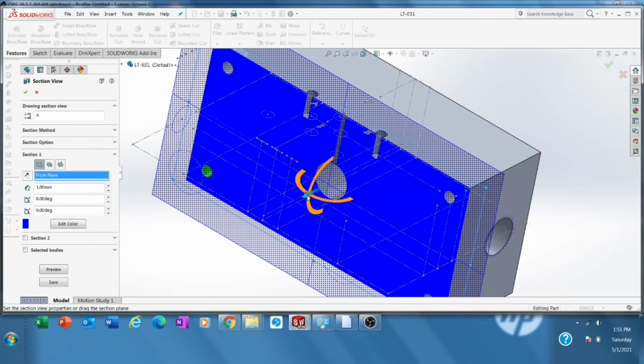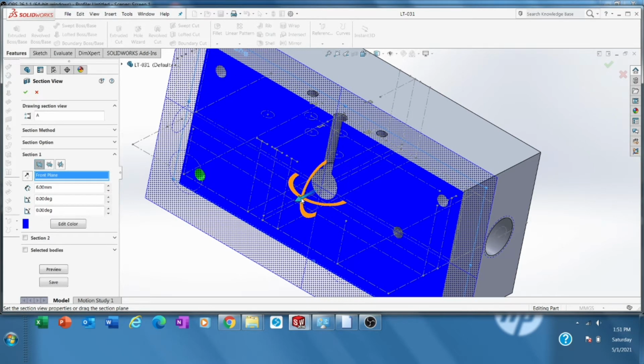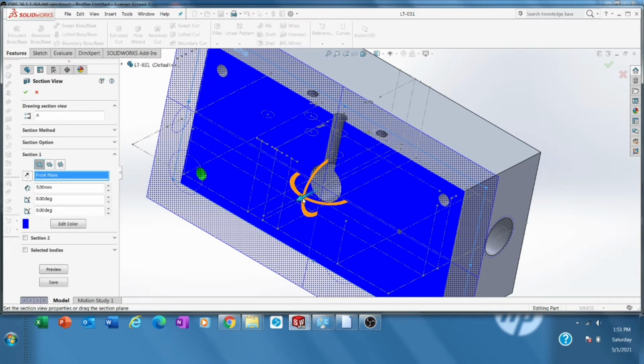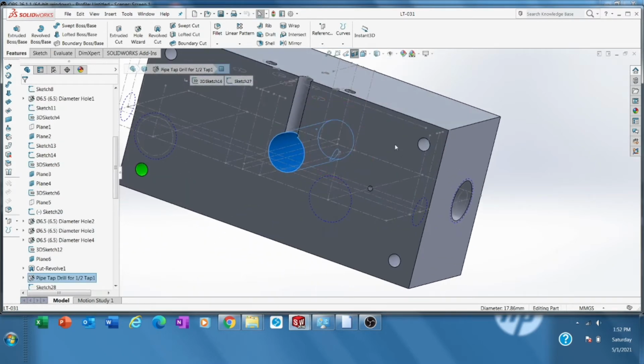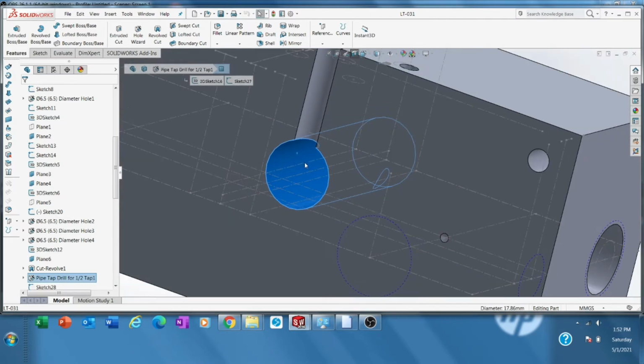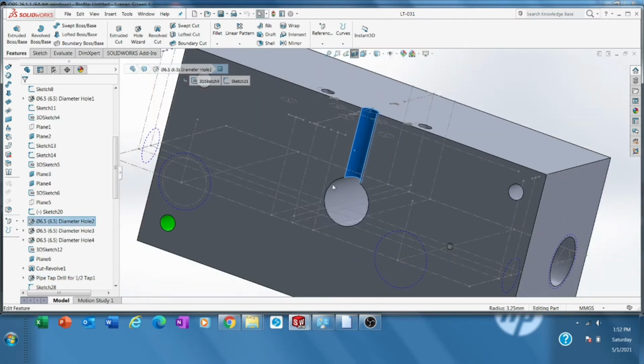Let's say, for example, this one. Okay, so we check this one, what it is. There is a P port flowing there, and then the fluid will flow up. There is no chance of this port P flowing to the left or to the right, so the only chance is up, to the directional valve port that I will explain later on. Okay, this is for the port P.